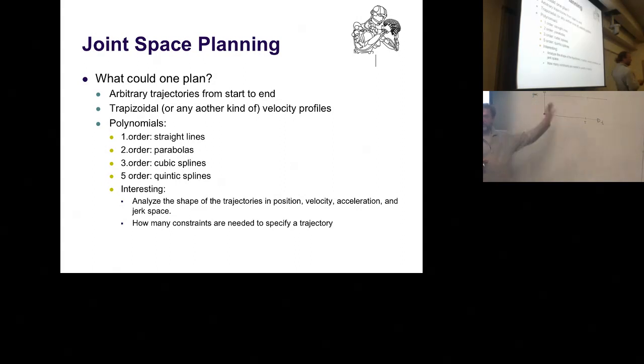The moment you draw it like this, you can actually make stuff up. Okay, how about that? Very reasonable. It's a straight line. How do we go there? What becomes interesting in all these considerations, given that we often want to use velocity and acceleration signals for a decent controller, is to look at velocity and acceleration signals as well. So we also look at x dot over time, and we look at x double dot.